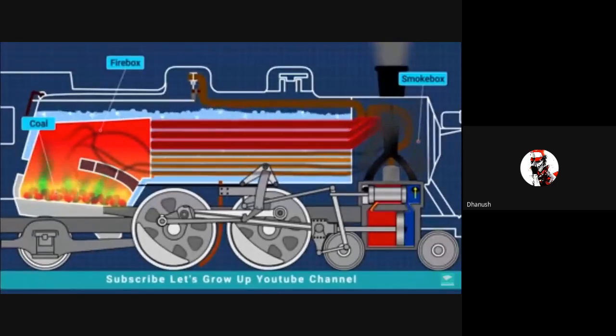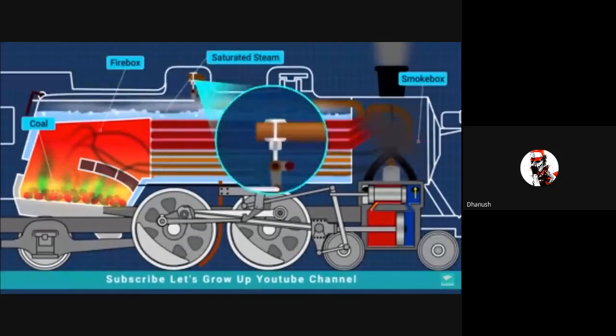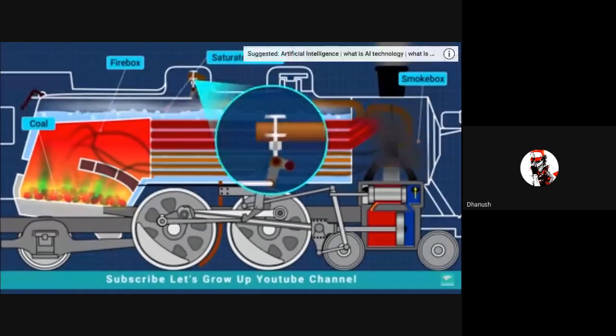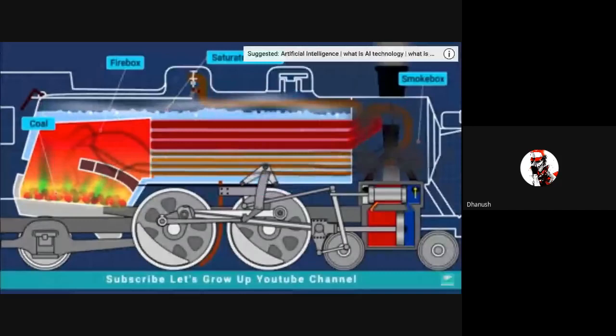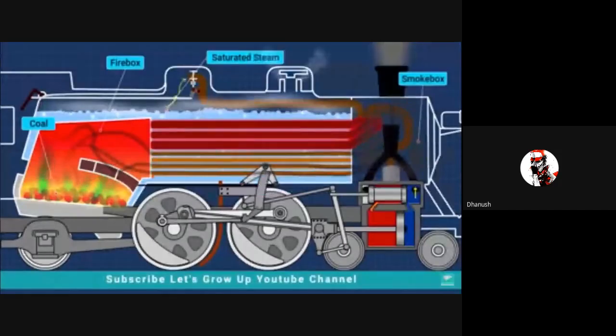As water becomes hotter, it turns into saturated steam, which collects above the water. The regulator valve, which is situated in the dome, controls the passage of the steam to the cylinders. The safety valves on top of the boiler release the steam if the pressure rises to a dangerous level.